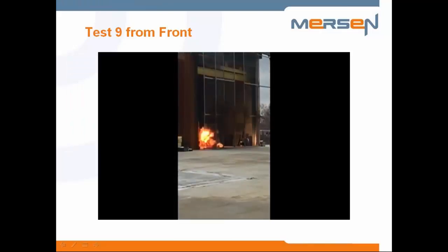This is from the control room about 100 yards away, and what we see here is a pretty big explosion. In that case there was no high-speed grounding switch, and the lab shut the test down after 500 milliseconds, well before the fuse could clear.